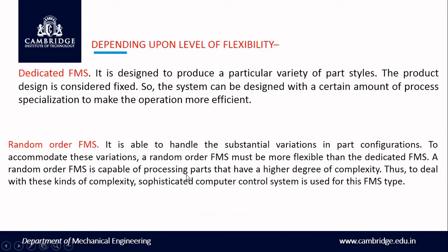Another thing is that, depending on the level of flexibility, there are two types: the dedicated FMS, that is the dedicated flexible manufacturing system, and the random order FMS. What is dedicated? It is designed to produce a particular variety of part styles. The product design is considered fixed, so the system can be designed with a certain amount of process specialization to make the operation more efficient. That is called dedicated FMS.